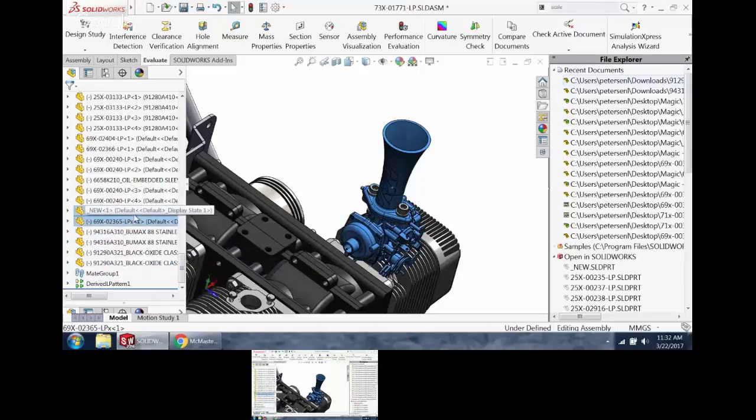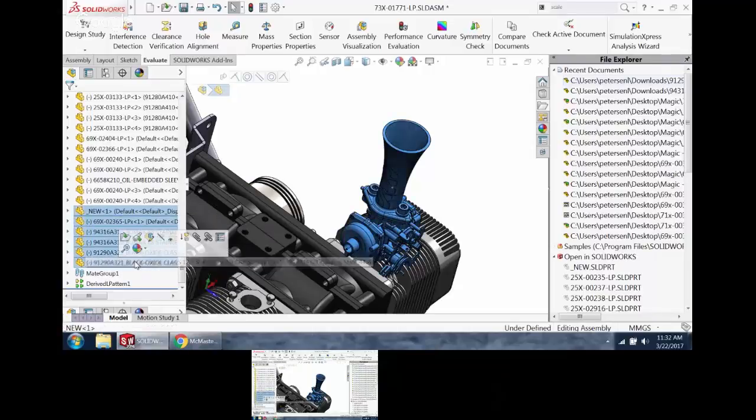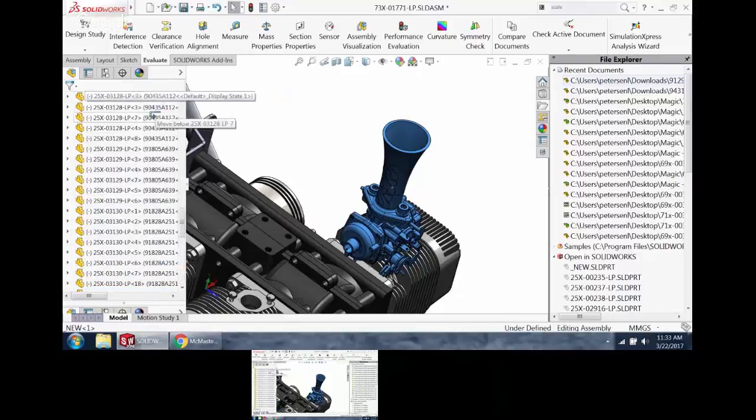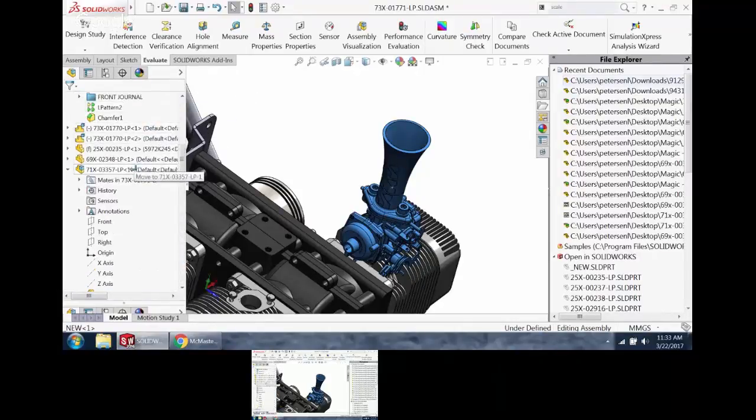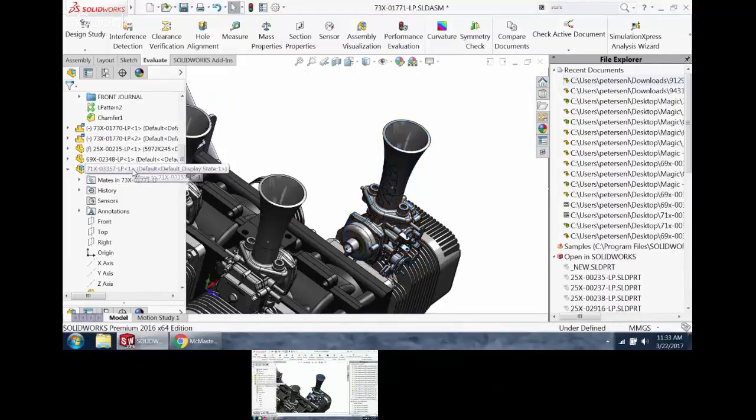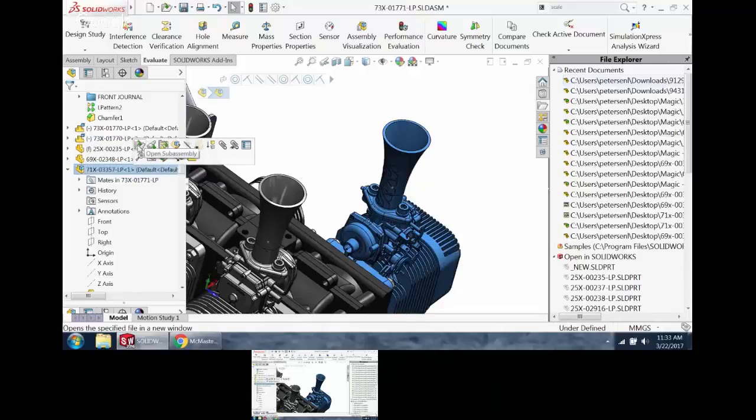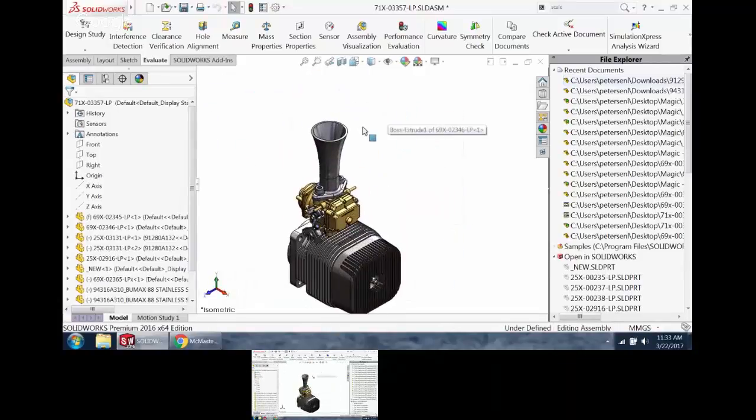Lars, could you go over your advice on tool features using McMaster-Carr? Sure. Let me finish this up. I'm just clicking all those parts and dragging them and dropping them into a subassembly to change their location. So I put them in at the top level and then remembered, oh no, I don't want them. You can click and drag stuff in and out of subassemblies when you're at the top level.